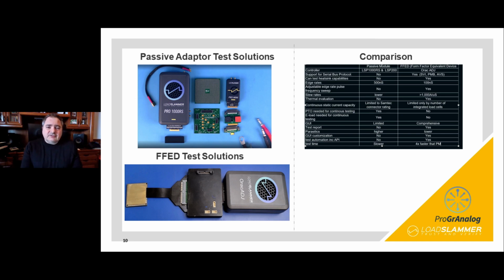If you need to do continuous current or OCP testing, then you'd add what we call the PTO, which is the red and black cube on it, and then you can see some cable tips at the end that would plug into that, and that allows you to connect the top of the passive module to an electronic load in your lab. So you can do additional constant current testing as well, so stress testing your OCP or just getting a basic efficiency measurement.